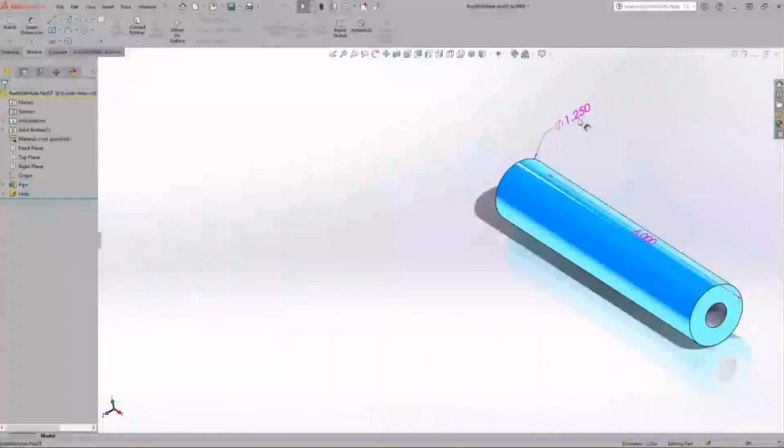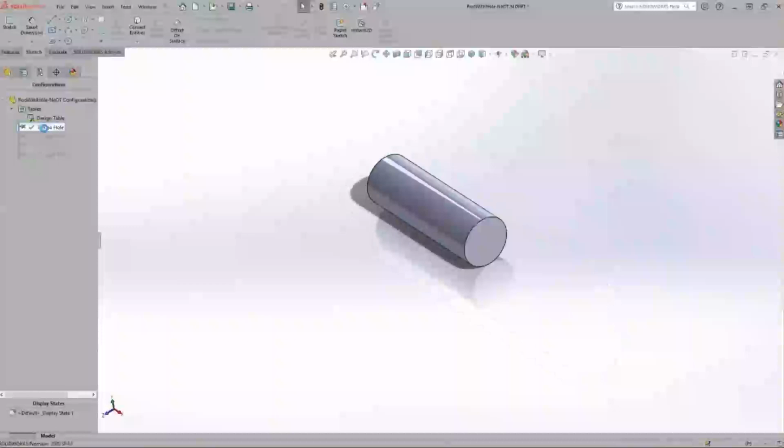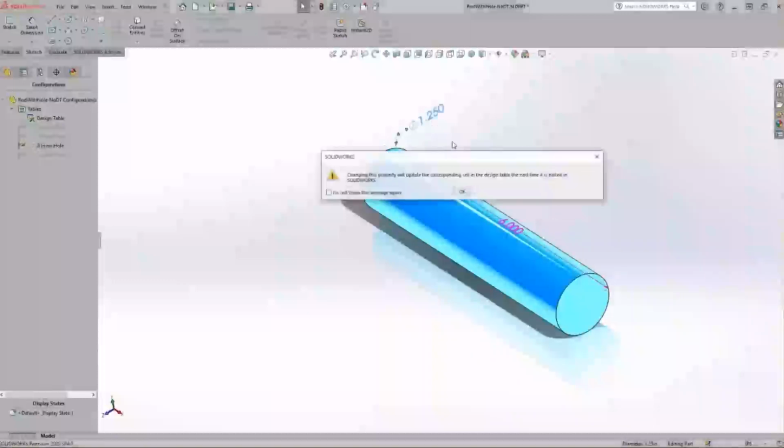So once you're done, click into SolidWorks, makes the change, and we can cycle through them. So it is fairly easy to do as long as you're careful, at least in my experience. Just be slow, be deliberate. Something I'll talk about here in just a moment. I want to point out the color of those dimensions. Notice they are pink. That's a long old setting inside of SolidWorks that any dimension that's controlled via a design table gets that bright pink color.